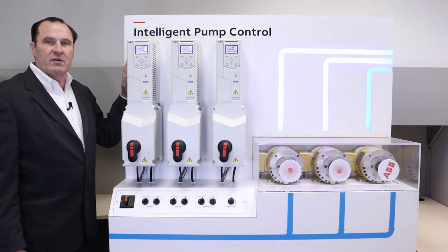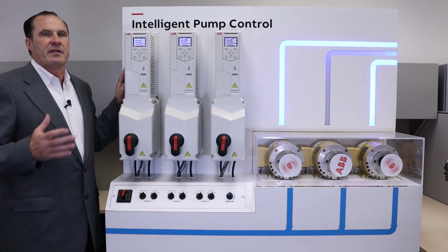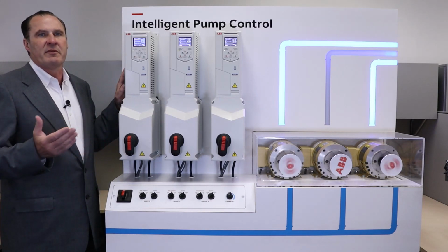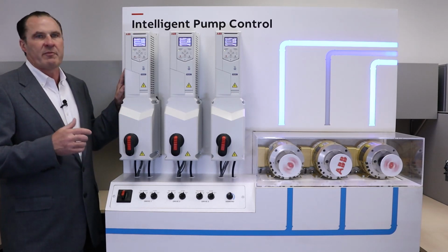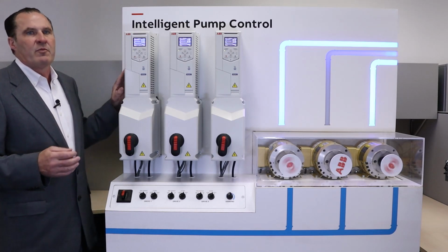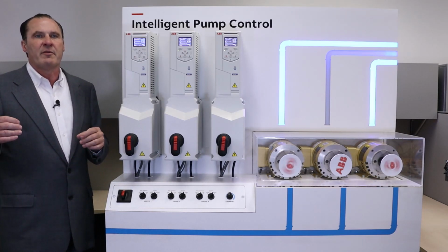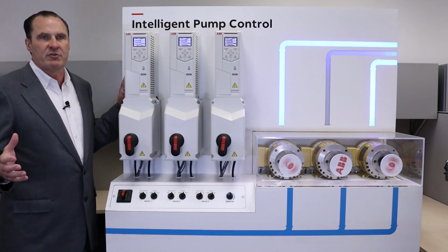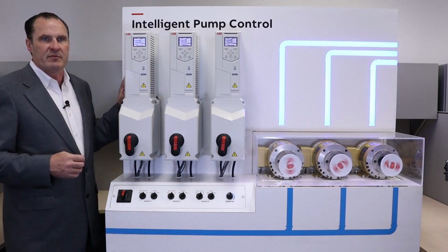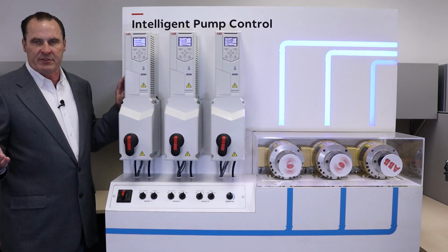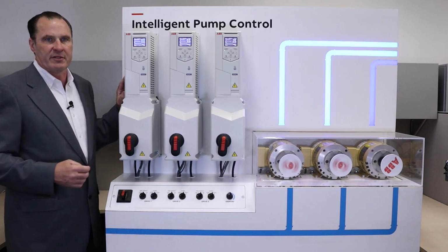Now let's take a look at the individual drives and look at actual programming of the parameters into the drives. Programming the ACH 580 Intelligent Pump Control System is simplified through the use of an inverter-to-inverter communication link. This link allows for automatic parameter synchronization between the drives. Program each individual drive for its connected individual pump and motor characteristics, then program one drive for the intelligent pump control features that you want. That drive will automatically update the other drives in the system. Any drive can be programmed to be a master drive. The master drive controls the other drives through the inverter-to-inverter communication link.